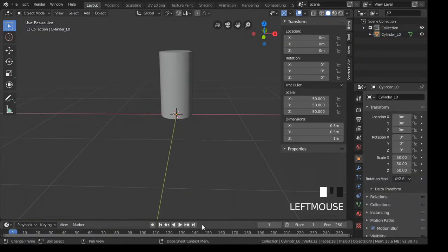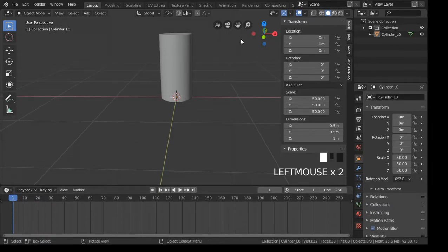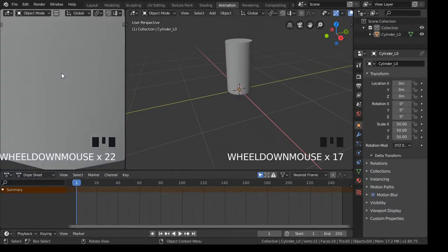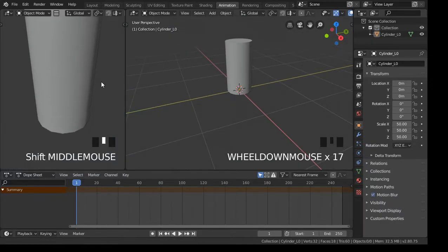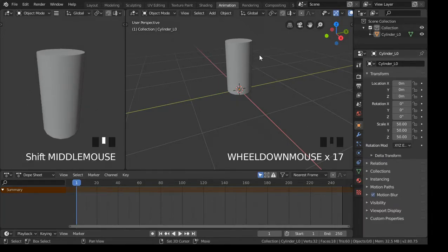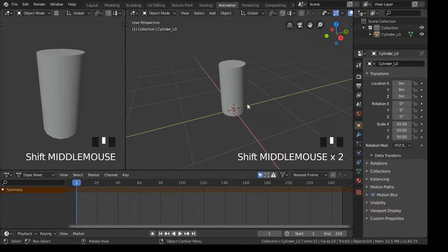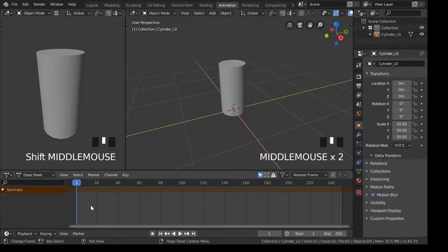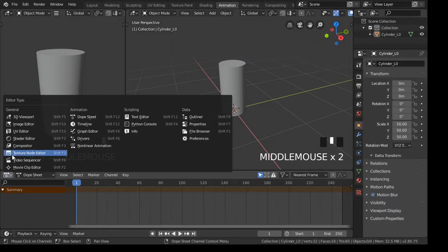You can animate from your layout tab, but if you want to use your animation tab, I'll explain what we're looking at here. So since Blender 2.8 uses the Eevee engine, this is your general viewport right here with your grid, and this one over here is the render view. So if you were in Eevee instead of Cycles, then what you're rendering would be shown over here. And then this is your timeline based off of a dope sheet. Well, for TMTK animation to work, you can't use the dope sheet. You want to be in the timeline.